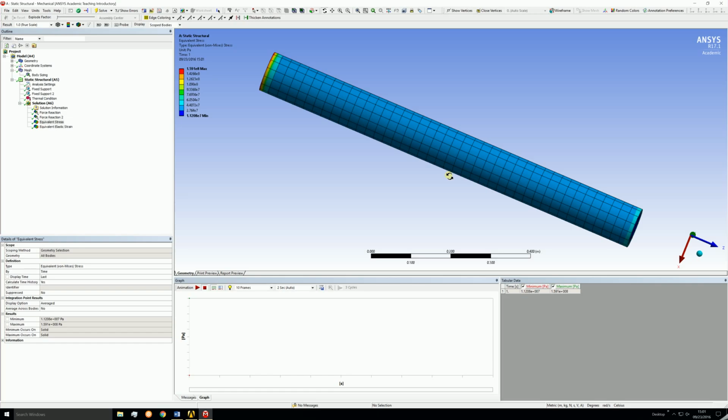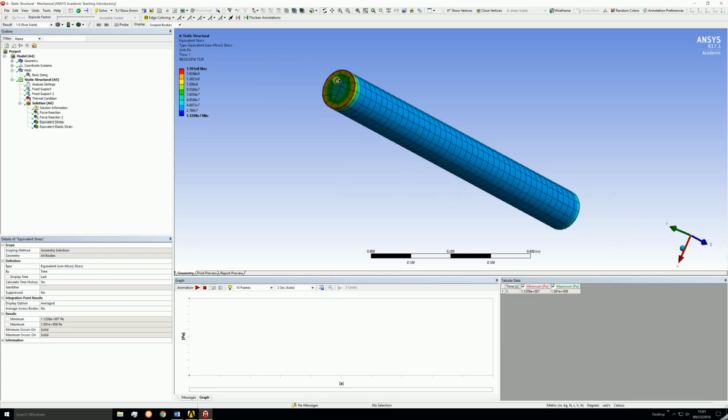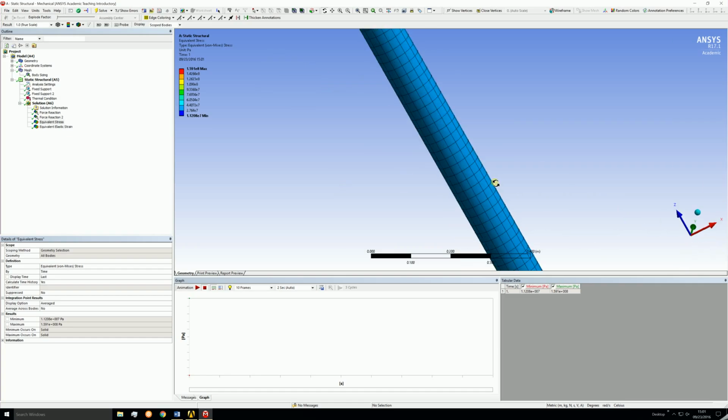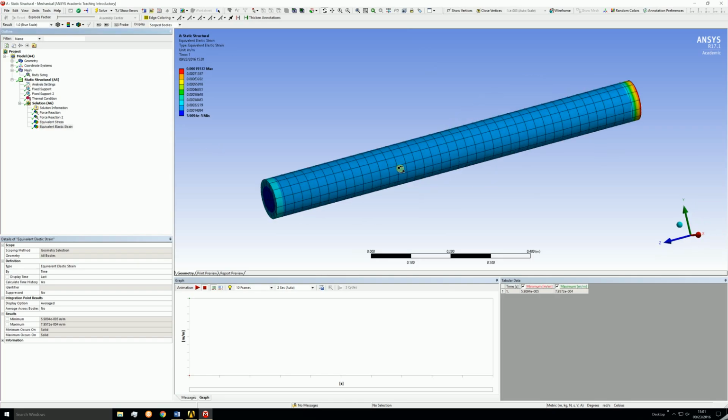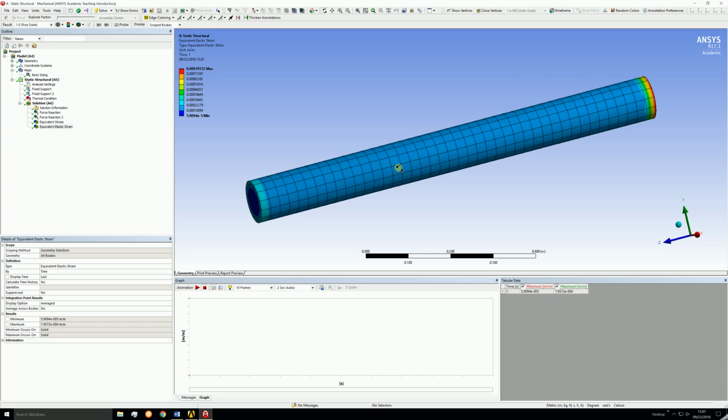Anyway, stress is the amount of force per unit area, and that's what happens when a force is applied to a surface. Here it's the ends of the bar that the forces are being applied to. Now, strain is a change in length of a material divided by its original length. It measures how far 1 meter of bar stretches, in meters, for every meter of unstretched bar. If you want to know more, look up engineering stress and engineering strain on Wikipedia.